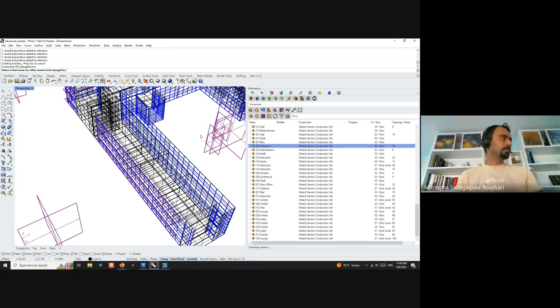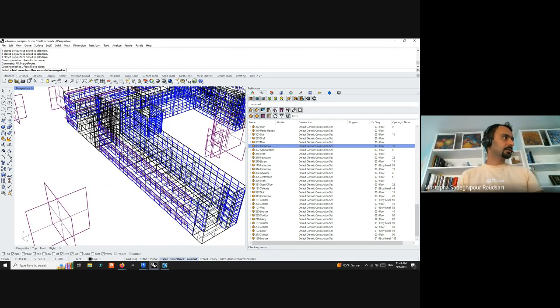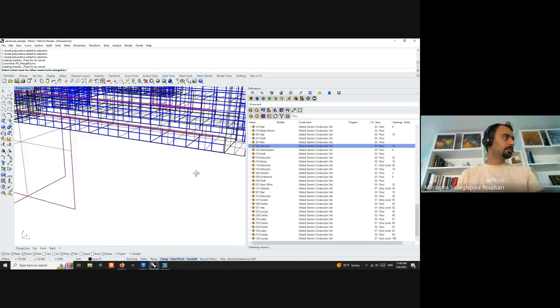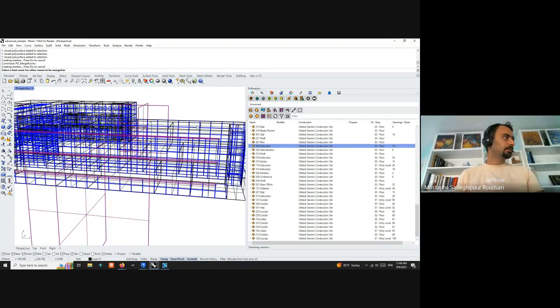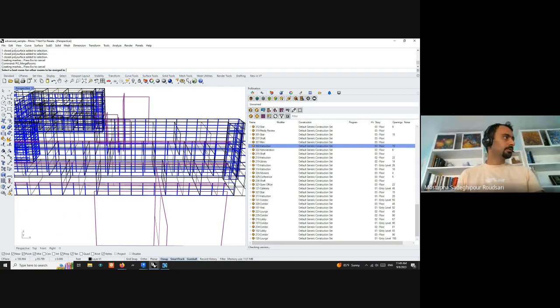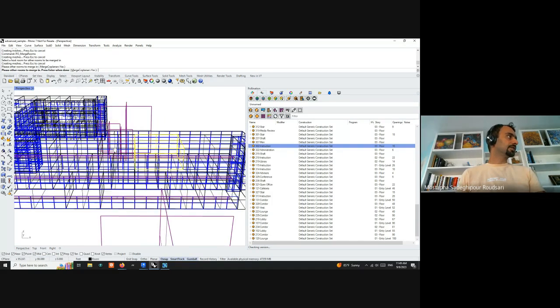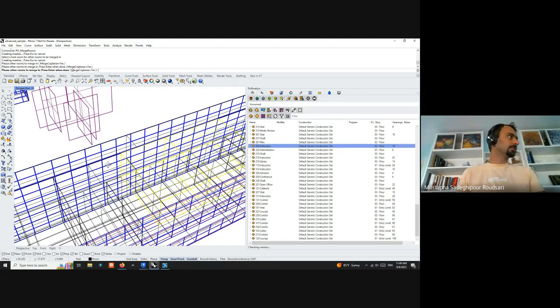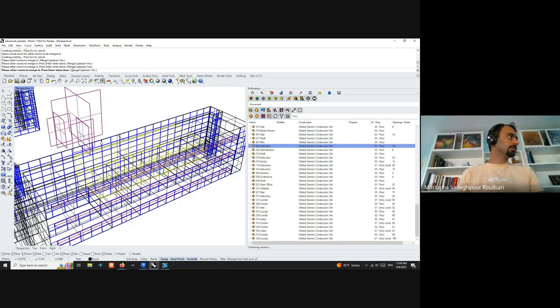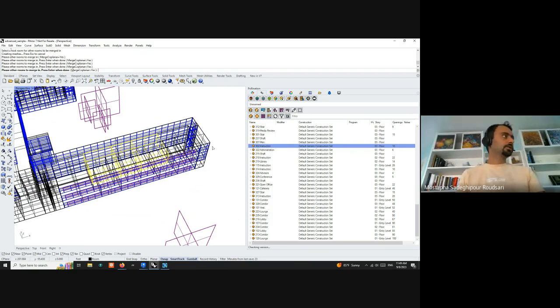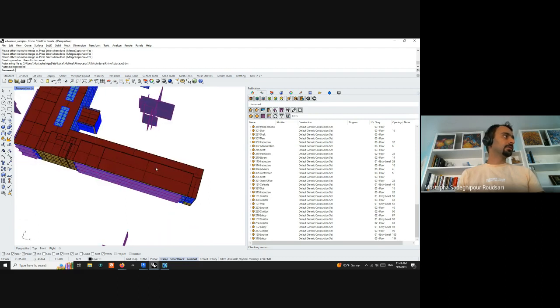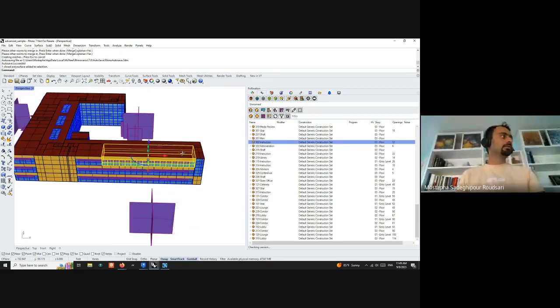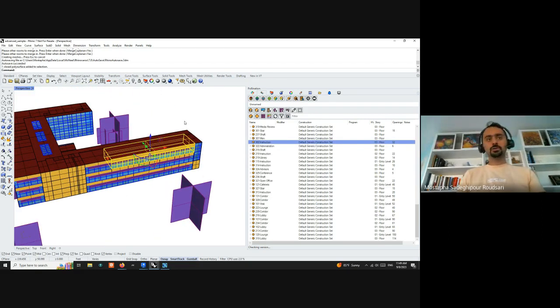This command doesn't like my pre-selection for some reason, so I'll just go here and select this one. You have to select the first one and then merge it with the rest, because it wants to know where to get the programs and all those. When I do this, it will merge them together. Now you see that the 3, 4 rooms I had is now changed to a single room.